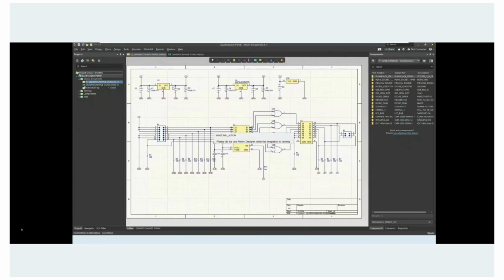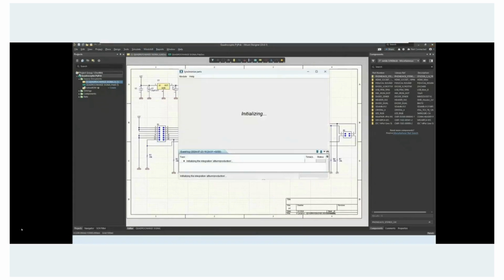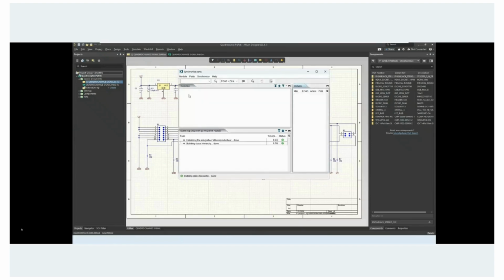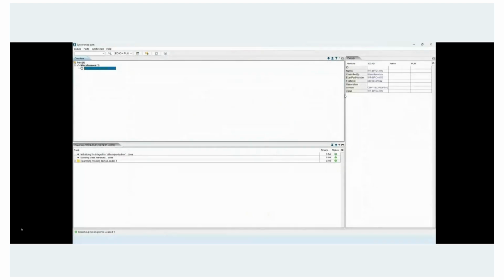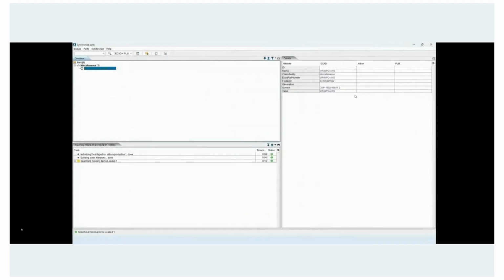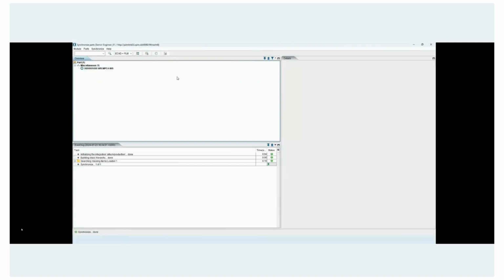Now, when it comes to adding parts to Windchill, you can either add the parts to Windchill first, the new part, or through the part synchronization process that we have, you can add the part in CAD first and then have it synchronized to Windchill, and then it will add the new part in Windchill. And that's what you're seeing here. This part exists only in the ECAD library, the MPC4 right now. The engineers created it.